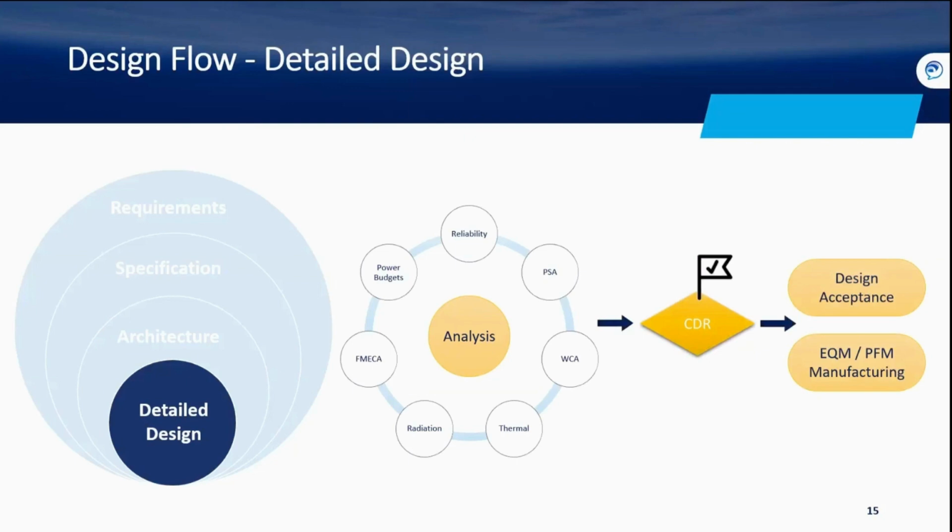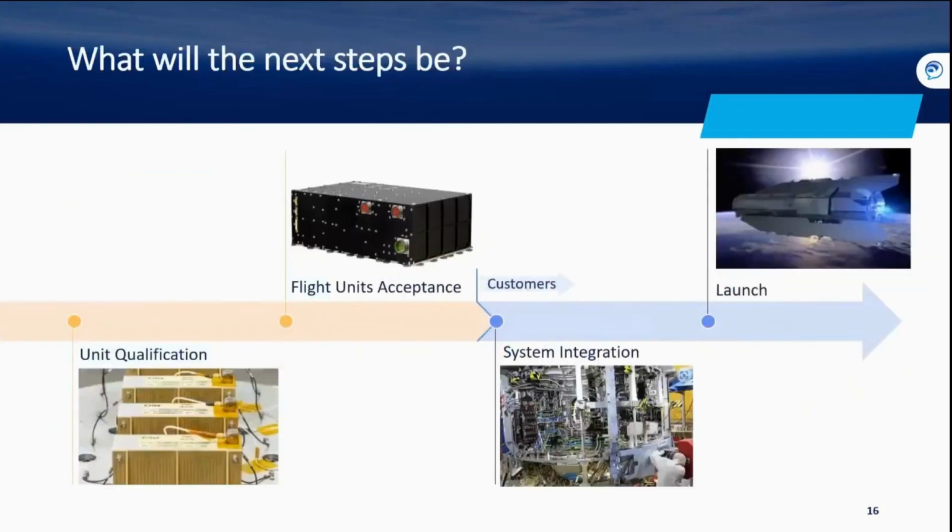Well, we can start with the kickoff of our very first model. At this point, we have 3 standards. We have electrical models, qualification models, and flight models. So the first 2 stand for system performance and system qualification, and the flight model is the one that will be launched. So let's take a closer look at the next steps for the flight model.